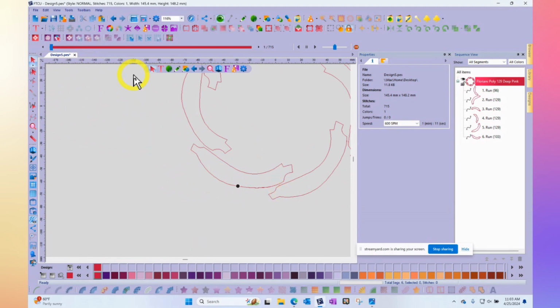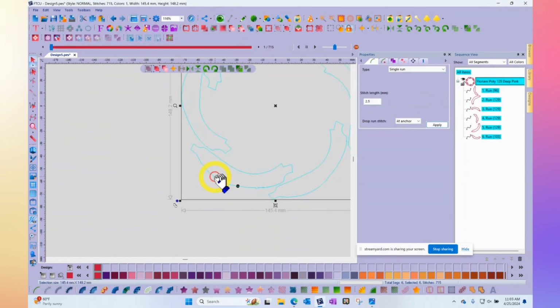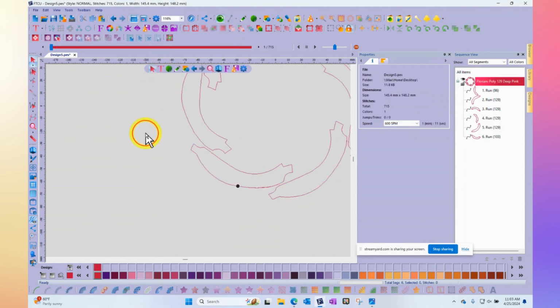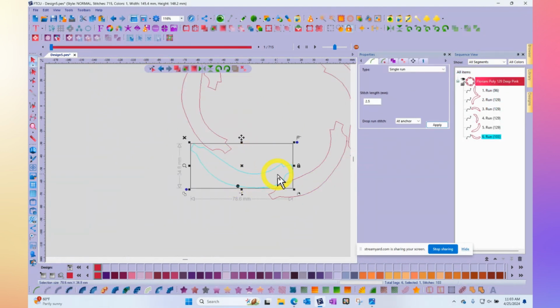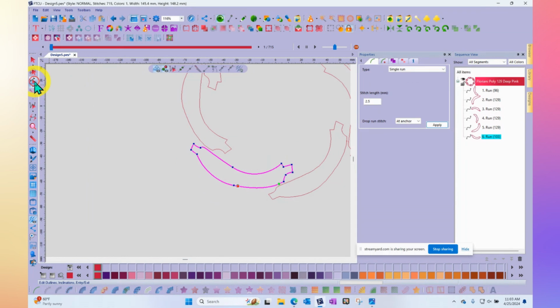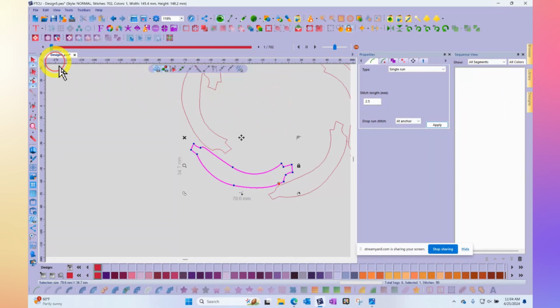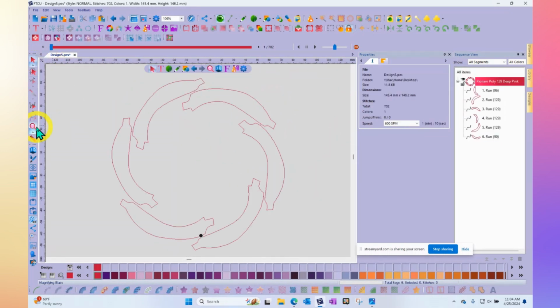So yeah, if you want to take control of the entry exits of any of the shapes independently, so apparently this is the last one, and when it goes around, if you wanted it to actually only go once around and stop there, because right now it's walking to there and stopping, once again, you can select the shape. Now it's all grouped together. So I'm just going to click on ungroup so that I can select that one piece. And then I come here and I can move that red exit to match up with the green entry. And that way it would be kind of just a single ply all the way around. Yeah.